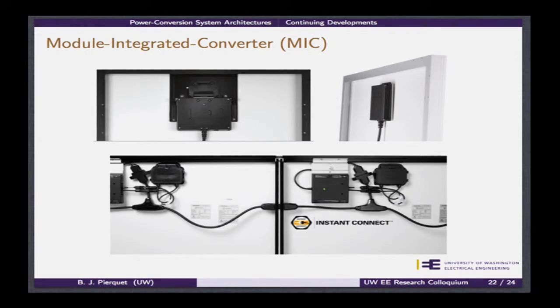You can make modules with 3 separate strings from 3 separate bins and not have to worry about the matching. To get a high-power module, to get the top cells all from the same bin is much more expensive than getting the less expensive ones. And so if they can mix and match to control their own inventory and power output, that's something they're definitely going to be very happy with.